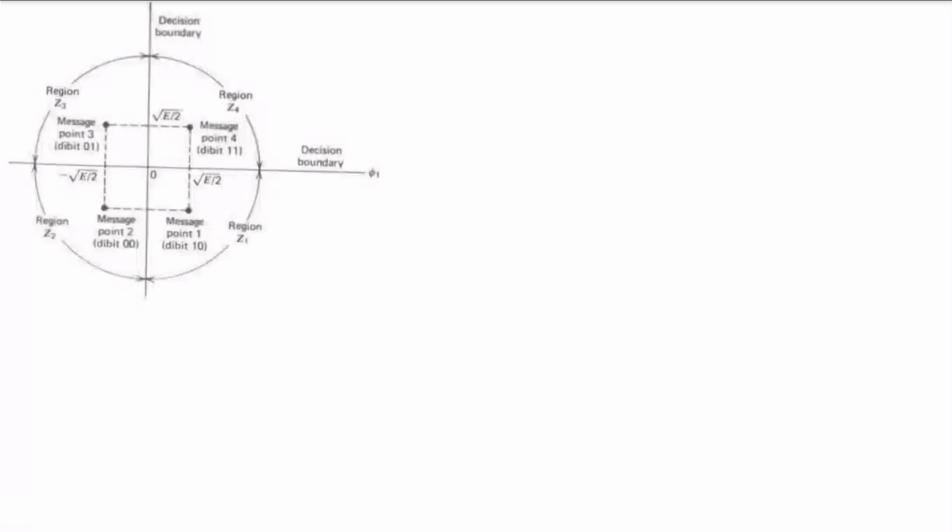Two binary bits together form one symbol, that is a dibit. If we combine two binary bits, 0 and 1, we can have four possible combinations: 00, 01, 10, and 11. So we can place these symbols in the phase of the carrier and transmit.